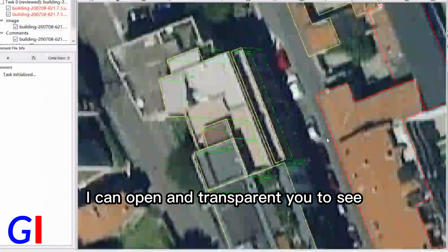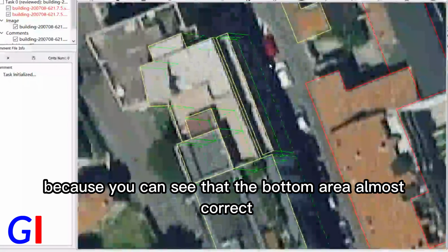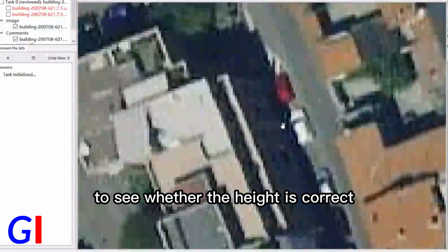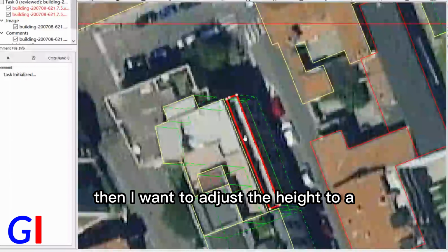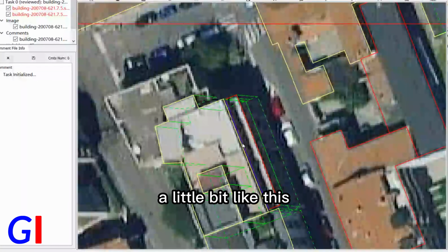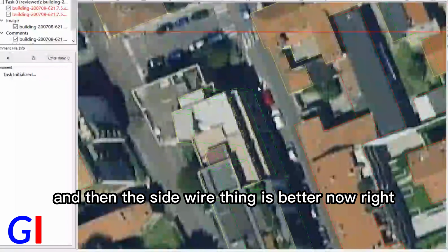I can open transparent to see. So it seems like I drew correctly, because you can see that the bottom area is almost correct. It will help you draw to the same bottom area, but you should check the side wall to see whether the height is correct. After checking, it's a little bit lower, so I want to adjust to a bigger height. I will just use the Alt dragging tool to adjust the height, a little bit like this. And then the side wall, I think, is better now.